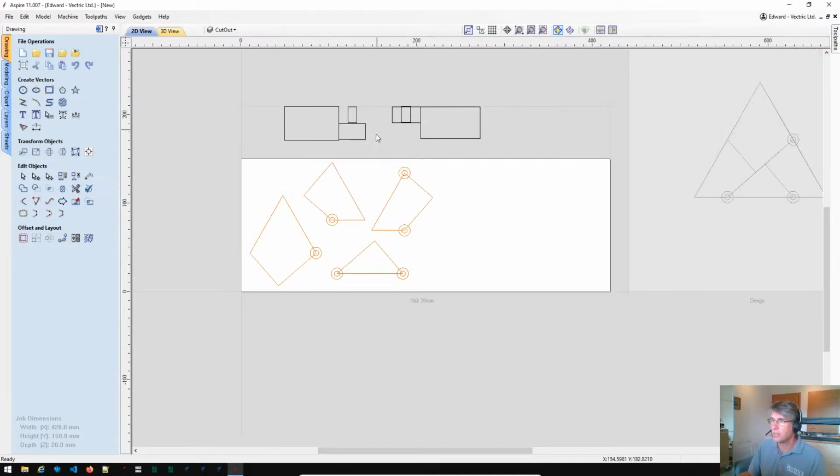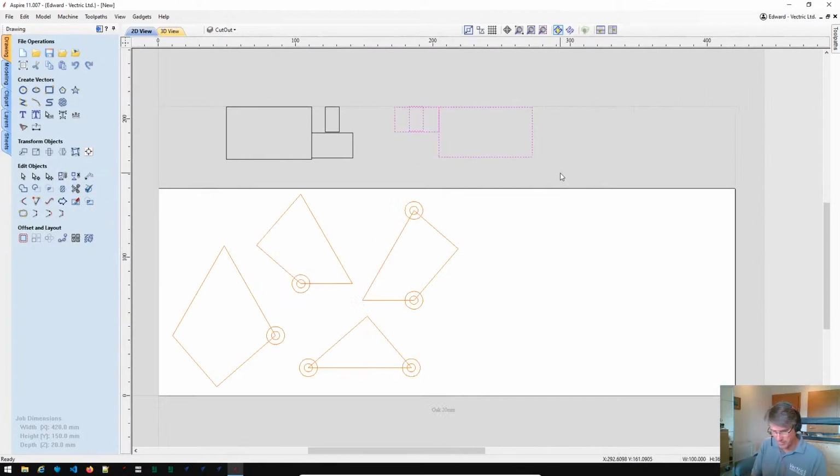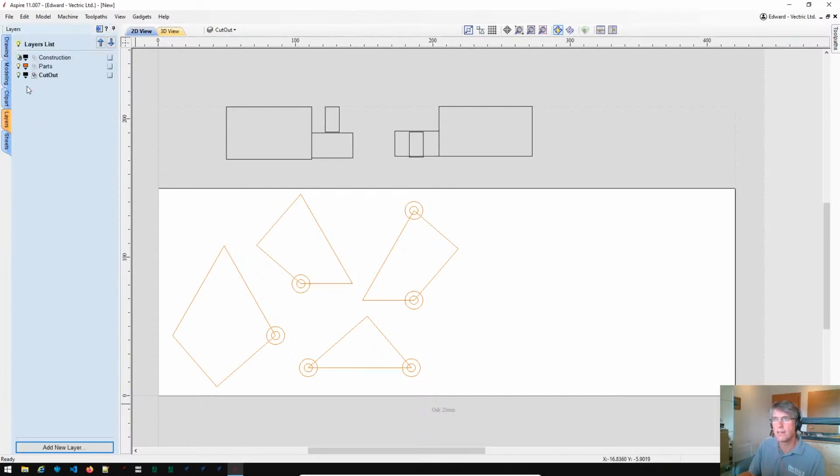Having done that, I think we can kind of relax. Then let's think about the toolpaths. This part now is going to be this way up, and we're going to cut down here. We want to pocket out all this area above the hinge on this one, and we want to pocket out the area either side of the pins to make the hinge on the other side. So I'm going to create a layer called pockets as well. And then finally, we're going to want to come back in and cut this hole out. So effectively, we're also going to want a layer called holes, where we'll come back in and just take out those holes.